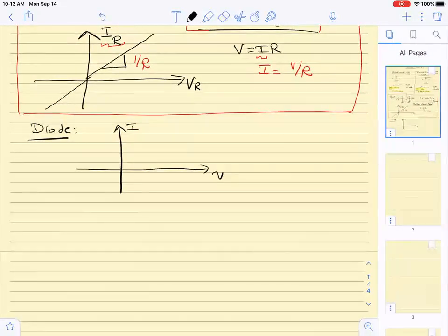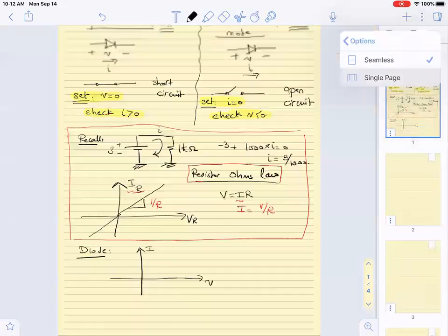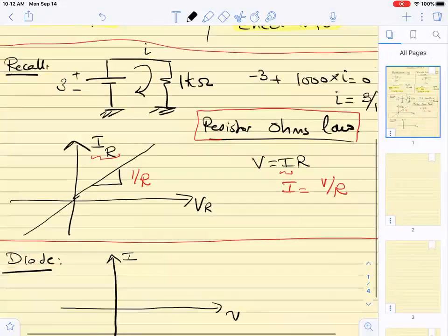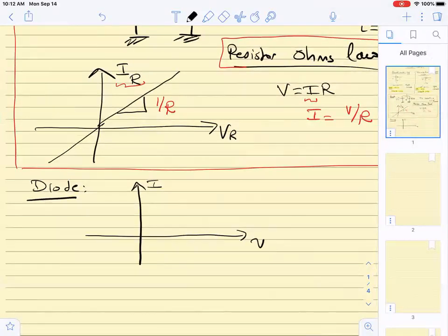Let us go back and redraw the circuit we had before with the resistor. I will have the diode here and the resistor. If the voltage at the anode is positive, this is going to cause the current flow to be similar to the direction of the current of the diode. And the diode will be what in this scenario? On. So if the diode has a positive voltage, the current will be what? Positive, and we don't know exactly how much.